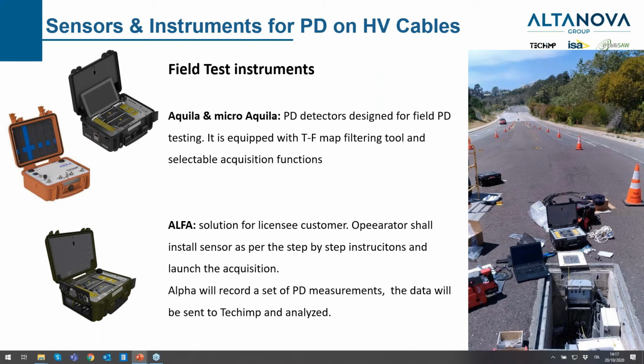All the ultra-wideband gives us the chance to save much more data about the PD signals we are detecting, and to apply filtering tools like the time frequency mapping to the acquired data. In this case, we can get rid of unwanted signals and the background noise in order to increase the sensitivity of the measurement we are doing.